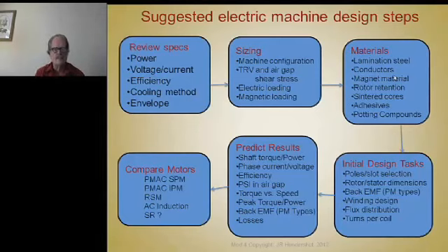It's done by some long-standing practices: the configuration of the machine, radial gap, axial flux, radial flux, transverse, and how it's packaged and mounted. Then, of course, we base this on tried and true, known sets of data on the torque per rotor volume and the air gap shear stress, and standards on electric loading, current densities, and magnetic loading.